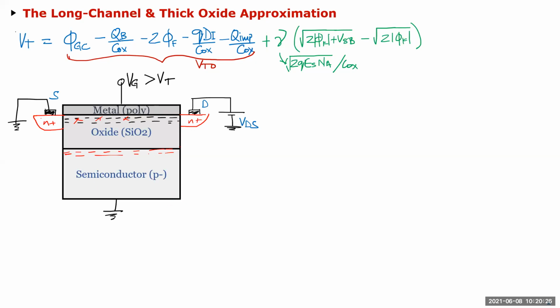So the source and drains are actually formed here. So this connection is actually here. So we use two N plus regions, and now the channel is formed. We actually want to make a switch out of it. So we said we're going to apply two N plus regions because we have created an N inversion layer.